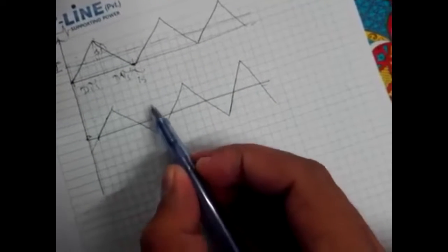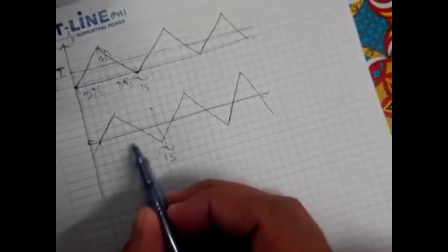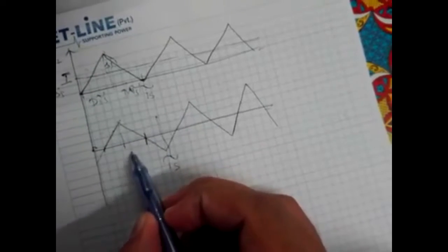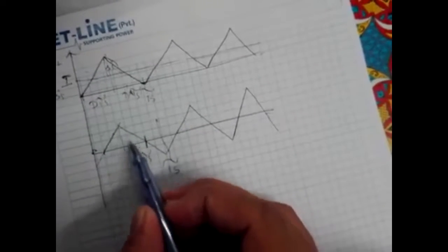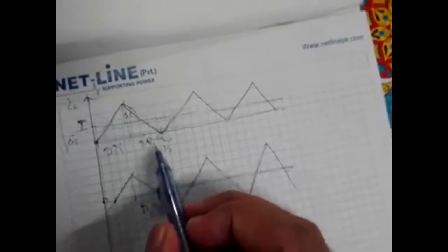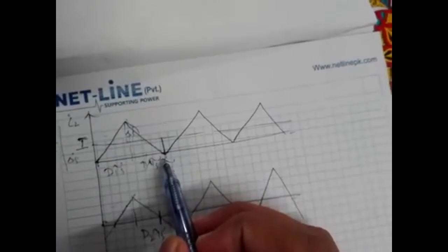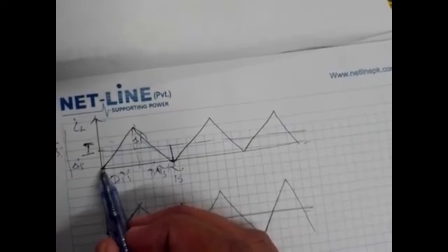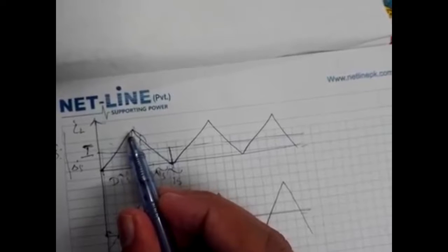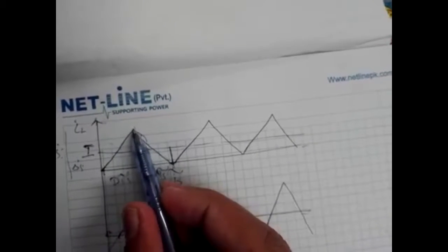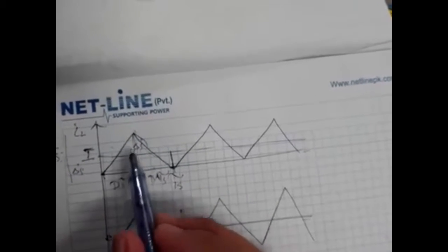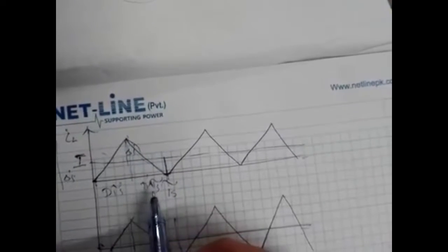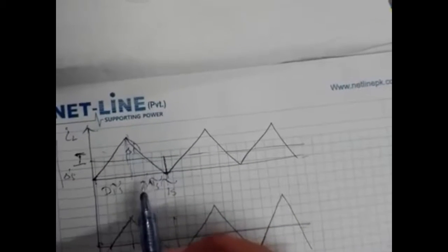As you see, the whole time is Ts here, and in such minimum time, the inductor current becomes de-energized. Before increasing the load resistance, we see that this is the Ts: the charging of the inductor is half of the Ts, and similarly the discharge of the inductor energy is half of the Ts.